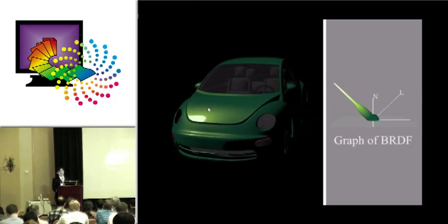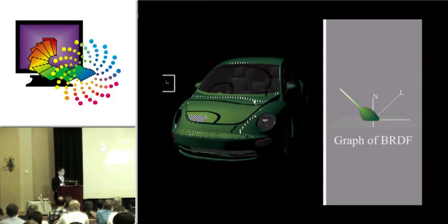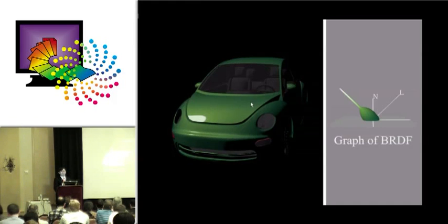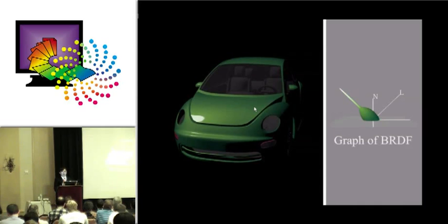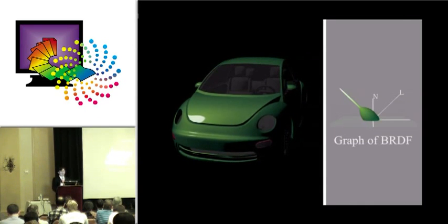the aspecular angle is visualized like a topographic map with contour lines. In this mode, the artist can drag the dashed contour lines representing travel to adjust the rate of change between face and flop. Dragging the edge of the checkered circle representing specular highlight will adjust the level of gloss, affecting the size of the highlight.